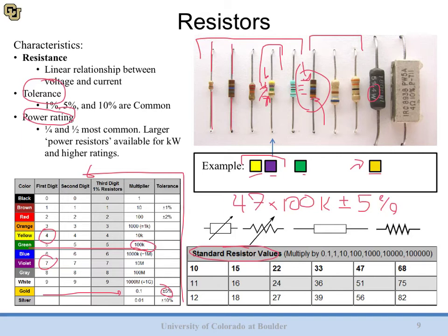So if you wanted to use, for example, a 30 ohm resistor, you'd either have to use a 33 or a 27 ohm, and these are all multiplied by 0.1, 1, 10, 100. So if you wanted a 500 ohm resistor, you could use 510 or 470 ohm. You're not going to get 500. So just be aware of that and pay attention to tolerances. That'll matter when you're building some timing circuits.